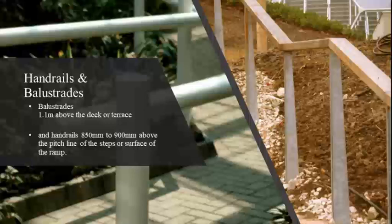The assessment should include the range of possible users, such as the very young, the very old, or the disabled. Remember that even a small change in level of 25 mm is enough to sprain an ankle or cause a fall, especially if it is not clearly visible. If the vertical drop to be protected is less than 600 mm, you may consider that it is sufficient to protect the drop with planting or perhaps a bench seat.